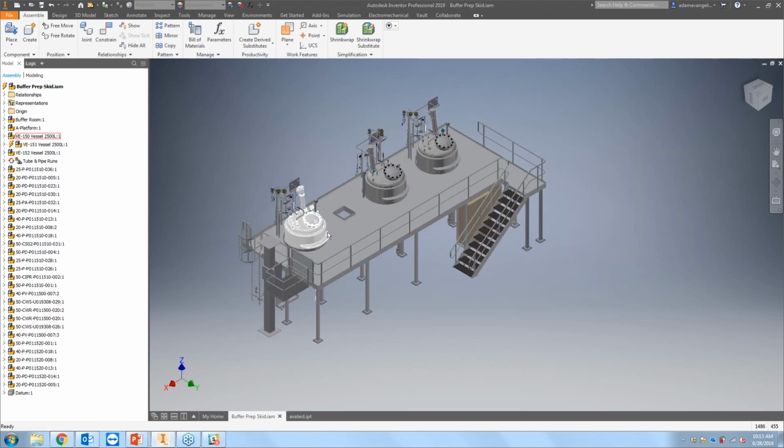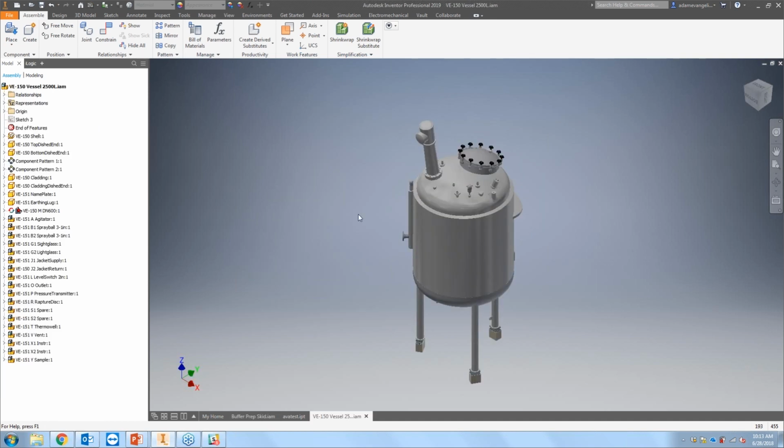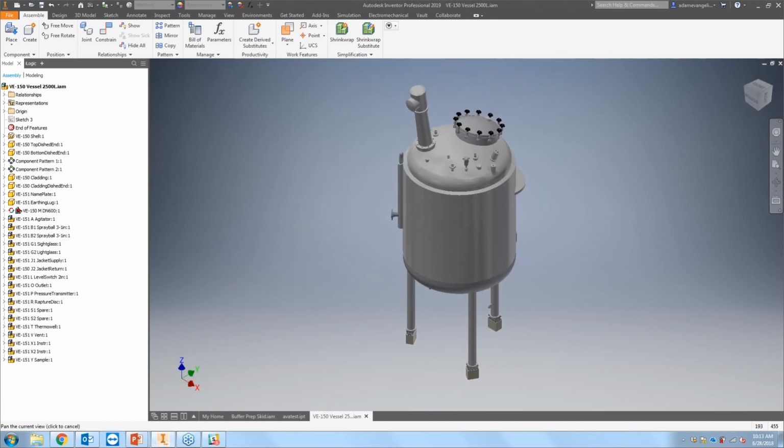That said, I'm going to go ahead and open up this part over here. We have a brand new assembly looking cute. Okay, and what are we talking about? Shrink wrap, of course. Over here in the assembly tab, you're only going to see the simplification options under the assembly tab inside of an assembly. If you don't see simplification, open up this little quick select menu here and make sure that your panels are enabled. In this case, simplification. Good stuff.